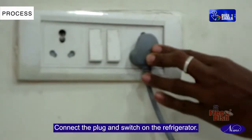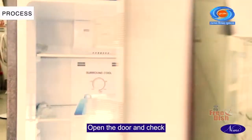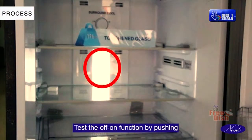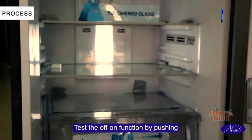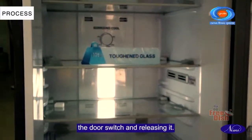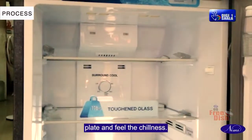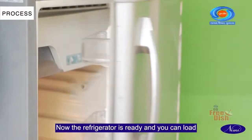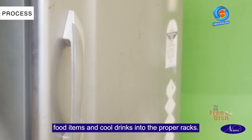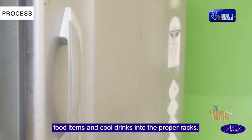Connect the plug and switch on the refrigerator. Open the door and check if the inner cabinet light is glowing. Test the off-on function by pushing the door switch and releasing it. After 10 minutes, touch the evaporator plate and feel the chillness. Now, the refrigerator is ready and you can load food items and cool drinks into the proper racks.